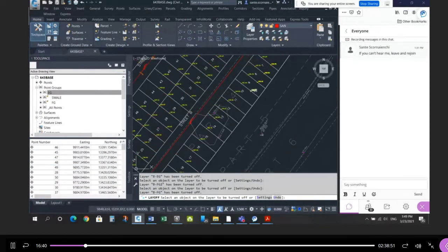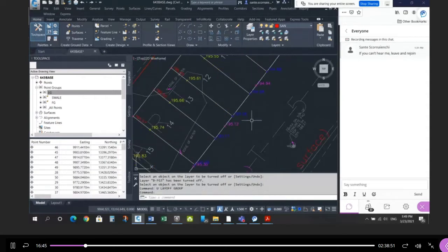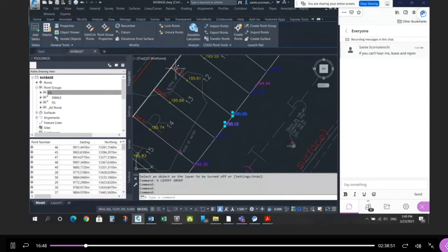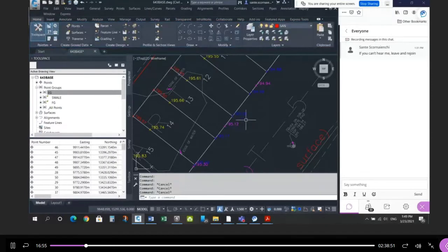And then there should be a layer for all the grading you did. So everything in yellow. Those are the different layers I asked you to produce: existing, proposed interpolated at the rear, proposed from the corridor at the front, and then proposed lot grading somewhere in between, right? So there were 4 layers.